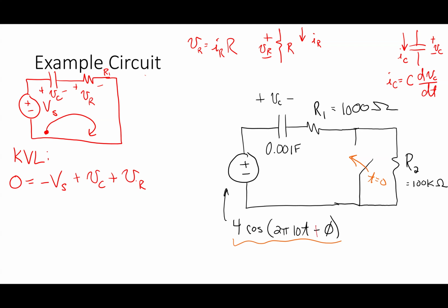I'm not putting any Ohm's law stuff in there. I'm not writing down what the voltage source is. I'm just saying the voltage across this element is V something, the voltage across this element is V something, and I basically write it out that way. Because the problem you guys make in circuits is there's possibly as many as 3 different signs that come in with each individual component. And it's real easy to mess it up if you're trying to skip steps in that process.